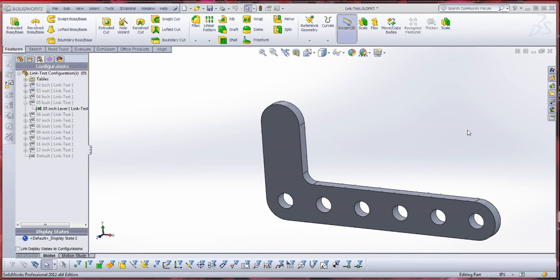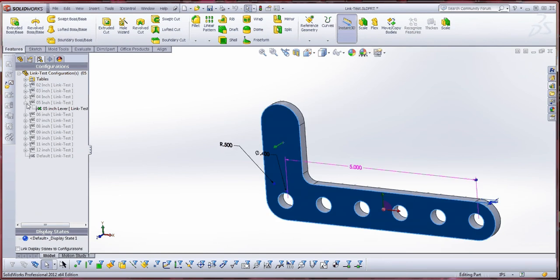And our assembly is going to be the control block assembly, and we're going to use the plane that's right down the middle of the slot to be able to define it that way. So let's do this. What we want to do is click into space, and you can use any configuration or derived configuration that's got the lever arm to it. So we're going to click on that one. This is arbitrary, the 5-inch lever. And we're going to go to sketch.